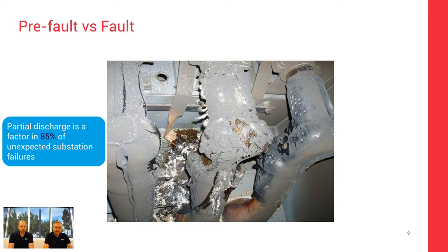If we're looking at this now, where we've got the situation, we could have an outage that lasts particularly weeks or months longer. We've got to replace these components. We've got to start looking at the cleaning. Potentially what you have when you get a failure that goes into the bus bars, into other areas, is you get secondary faults. So that starts coming up. So we could be looking at multiples, 3-4 times the cost of that.